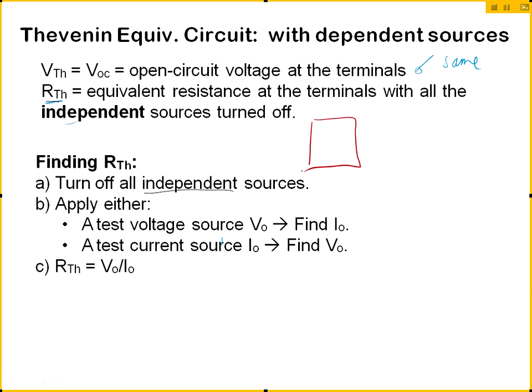Well, here's the original circuit, and this is our load. The load was over here, supposedly. As seen by the load, this is supposed to be equivalent to just one V Thevenin in series with one R Thevenin. Are we okay with that, as seen by the same load? The two should be equivalent regardless of what load we apply.